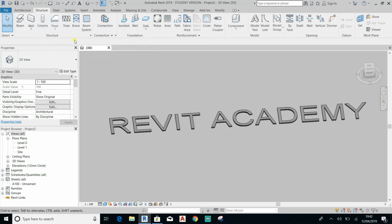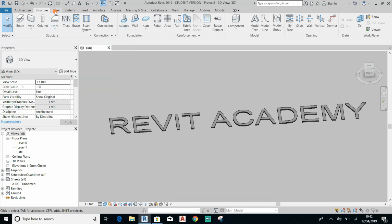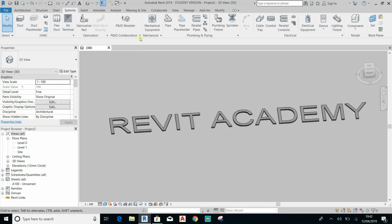The Structure tab, if you're an architect or a designer, this tab is used to import beams, walls, columns, structural floors, and you can apply foundations to the walls, and if you've got an isolated pad you can apply foundations to that as well. This tab, the Steel tab, is a new tab that has been introduced into the 2019 software, which was not available previously. The Systems tab is used by the mechanical, electrical and plumbing consultants.